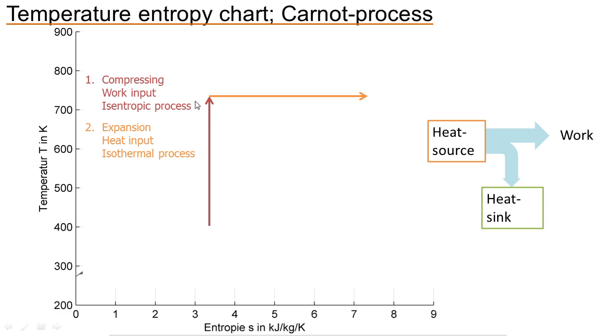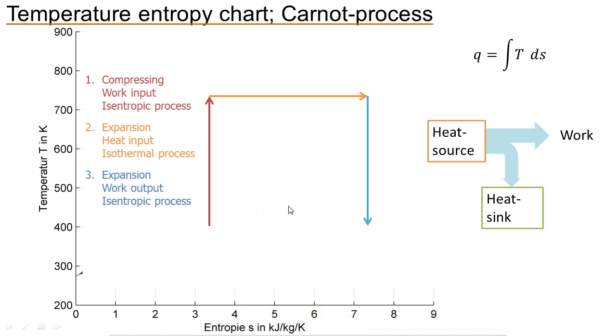This is possible. And if you want to know how much heat energy you put in here, just calculate the square under this line and you get the specific heat you put into this isothermal process here. Next thing is you let your gas expand again, but this time you pull the work out of this process and you do this insulated again, and there's no heat exchange.